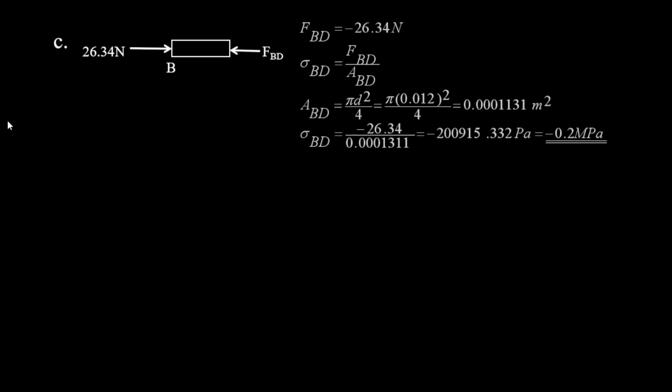That's 26.34. What is stress? Stress is just force over area. So force over area, we calculate nicely. Our headache is to find the area, and luckily for us, they gave us the diameter. They said we should assume the diameter of the shaft to be 1.2 centimeters, which we convert into meters, and then we get this to be our area. We get our force over area to be this. And if you still cut